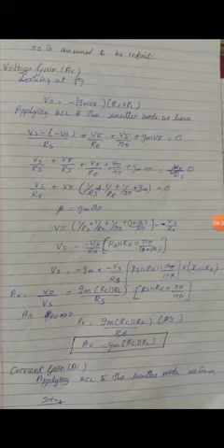And then our output voltage V0 is minus gm V pi, as we have already obtained. Instead of V pi, I substitute this expression, so we get V0 in terms of Vs. In the V pi equation we have minus Vs by RS, so when I substitute that, the voltage gain V0 by Vs can be obtained. AV equals gm into RC parallel with RL divided by RS into the parallel combination of RS, RE, R pi by 1 plus beta.